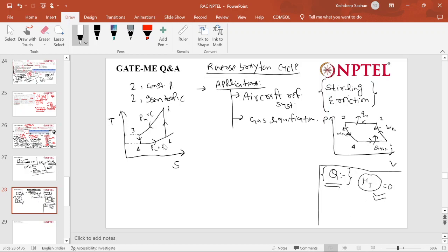So that is why we are not using an expansion valve as a throttling valve here. We are using a turbine. In a turbine, what is the advantage there? That turbine work you can give to this compressor, right? So compressor input is also decreased. And because it is air, with a turbine you can get more amount of work. But there it is liquid, in VCRS. So with liquid you can't get that much work, right?